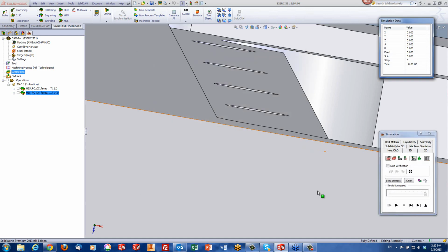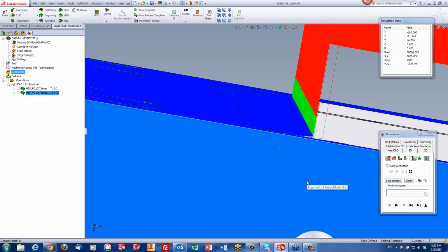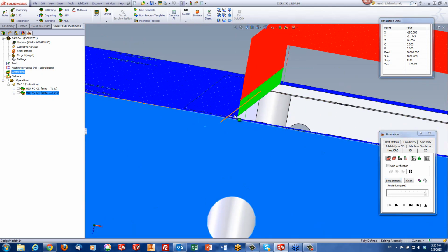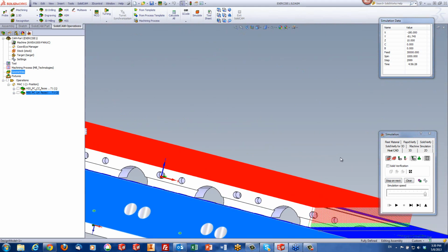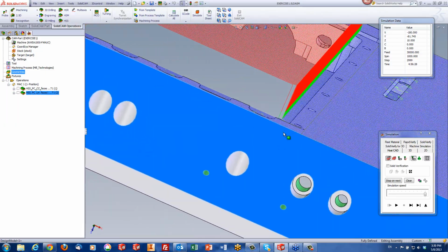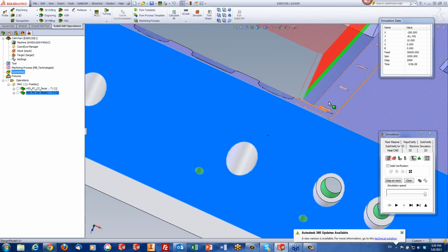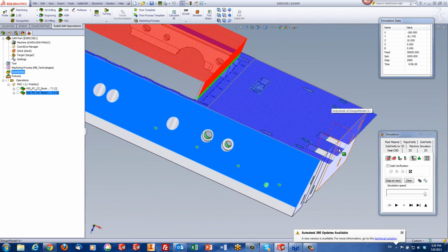Run my simulation. And this time you see it's actually going out 5 millimeters before starting the arc, going up, and at the other side, going back down again 5 millimeters before, doing the arc, finishing the arc 5 millimeters before, giving extension to that surface. Of course, at the end, we have the same extensions as well.